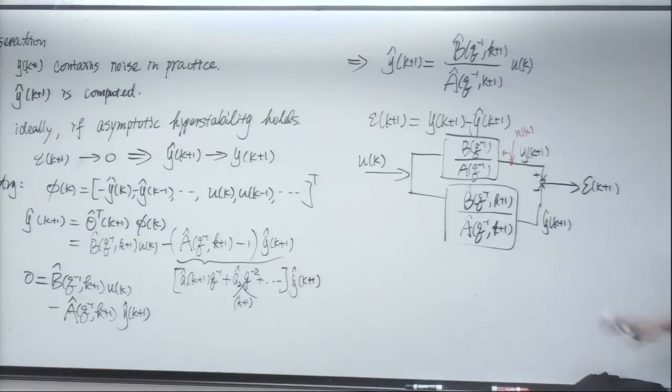All right? So when there is noise, we can actually expect nicer behavior using this structure because the noise doesn't go through these additional filtering in that stage. And this simple change of regressor vector actually makes a great significance in practical adaptive control and system identification.